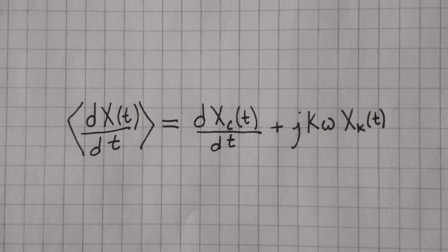The inclusion of these dynamic phasors will impact the model's accuracy, but allow the calculation of more complex systems than the single system analysis. This is accomplished by adding the dynamic phasor for the voltage component of the circuit. Once the dynamic phasor of the voltage is applied, we can follow the same steps as initially accomplished. The final expression is very similar to the initial solution, where G and A will now include the dynamic phasor components, making them more complex, as the dynamic phasor itself may be a complex variable.